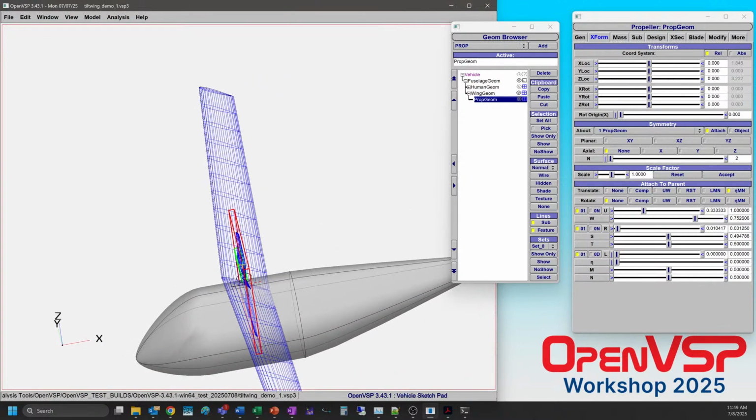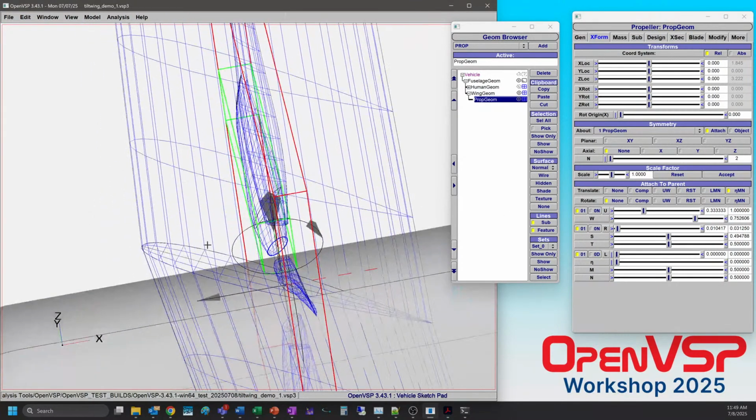Now, if we would have had, say, a multi-section wing, the U parameter gets broken up. By the U coordinate, I just mean the surface that represents the outside of this wing. So down here at this line along the chord at the root is U0.